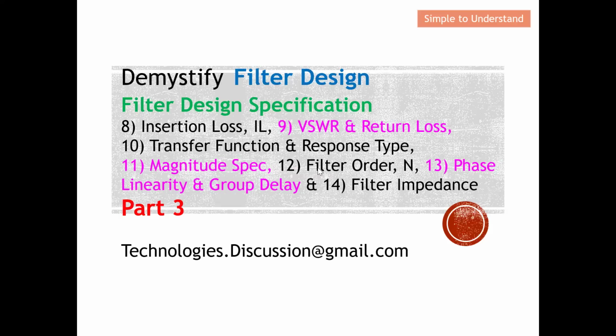The order of the filter: the larger the order, the larger the filter size, and hence the better the performance also in terms of the skirt of the filter. So we are going to discuss the filter order also. Next will be the phase linearity and group delay. Anything that we insert, besides reducing the signal strength, also adds delay. So we are going to take a close look at this parameter. Last but not least, the filter impedance. So we are going to discuss all these 7 in order to complete the full discussion on the filter design specification. This will be the Part 3 series discussion on filter design.